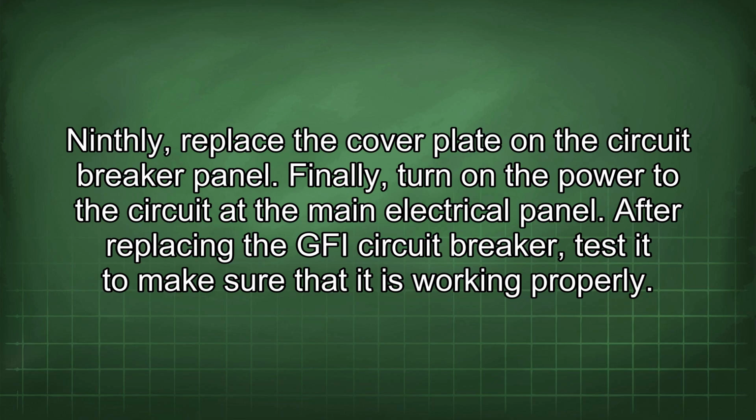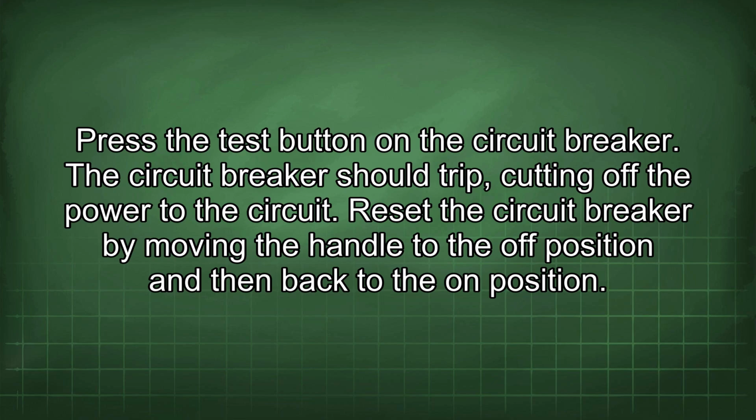After replacing the GFI circuit breaker, test it to make sure that it is working properly. Press the test button on the circuit breaker. The circuit breaker should trip, cutting off the power to the circuit. Reset the circuit breaker by moving the handle to the off position and then back to the on position.